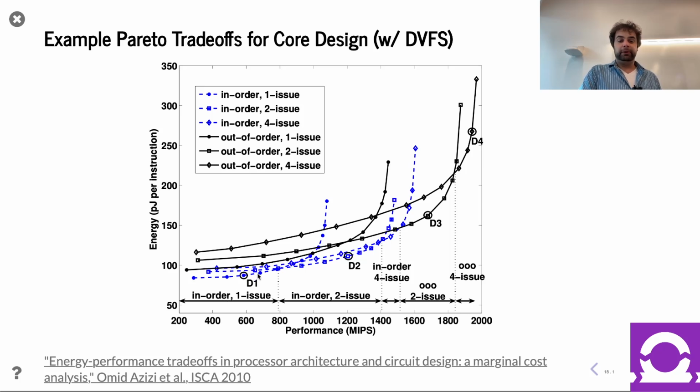For a really small energy consumption, it turns out the in-order 1 wide, unsurprisingly, does pretty good. If you want really high performance, even if you're willing to spend a lot of juice, not only do some of the in-order cores not even reach that fast, even when they do, you're actually better off using the big out-of-order core. I was saying that earlier, right? Sometimes going fast and big is actually better than really cranking frequency on an in-order core. So yes, if you trace the underside of this curve, because in this case down is better, but right is better rather than left for performance.